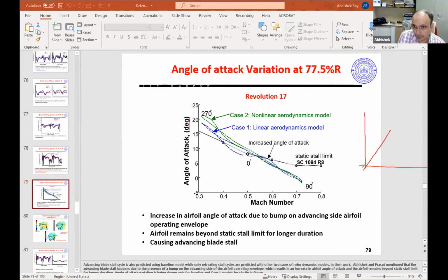So now on this, normally what happens? My lift will go and decrease like this, right? But with dynamic stall, because of this laminar separation bubble, my lift will actually continue to build up further. And then when this separation bubble leaves the airfoil, it will go off the trailing edge. At this juncture, the lift will suddenly drop like this. There will be a dramatic drop.